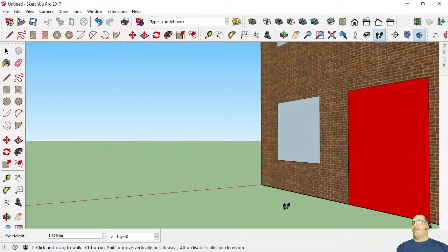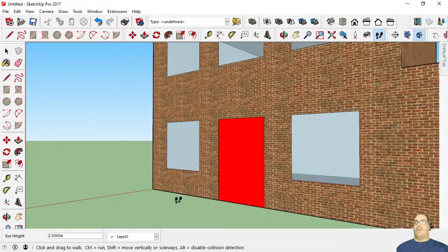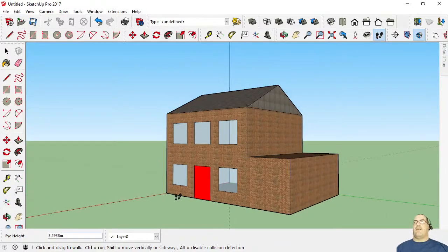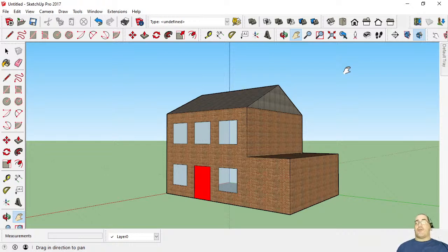Right, anyway, enough playing in a virtual world. We're here to learn how to build these things. So, that's the basics of buildings. Basically, you use polygons, you use your extruding tool to shape the building, you use your move tool and your lock to the up axes along midlines to do roofs and things, and you use your construction tools to line up windows and doors and other bits of roofs and such like.